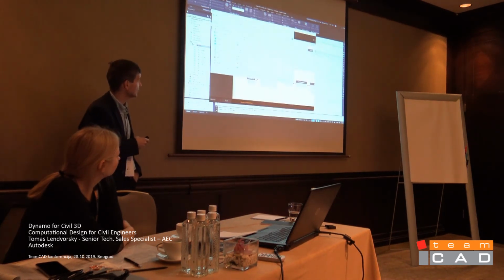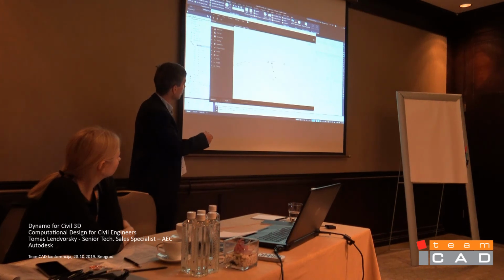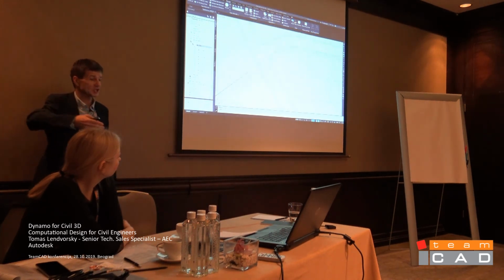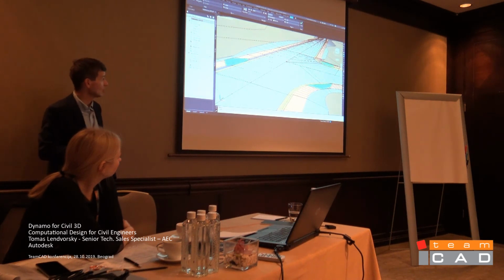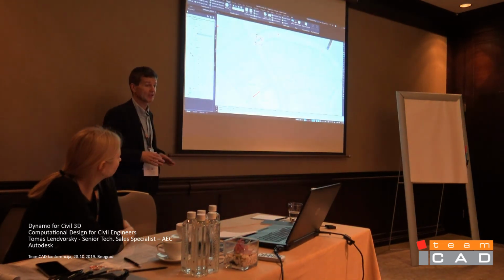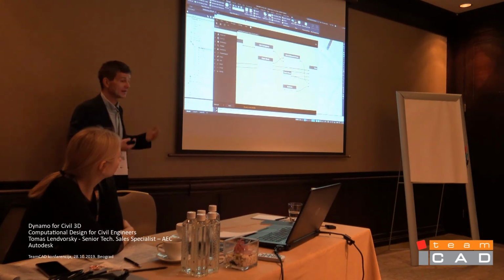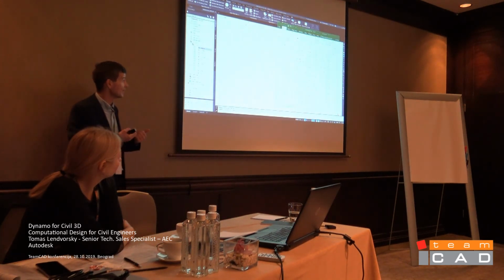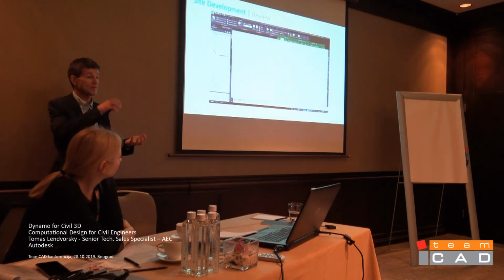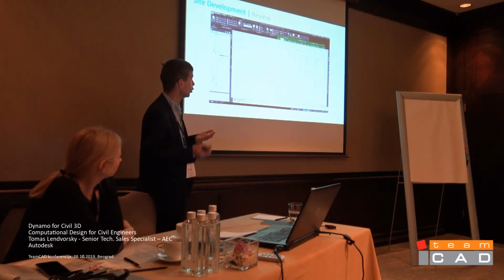Or you can just read this information from an Excel sheet, and you can run this, and then the system will automatically place these ramps based again on the Excel sheet where the location is and where it should be, and then the system will do everything automatically because it will place this line work, attach it to the surface, and create it. And the last one is a report, where you can get information out of your design to some Excel sheet, where you can get information automatically. Or you can maybe write some labels to your design. So it can really be something which you can automate.